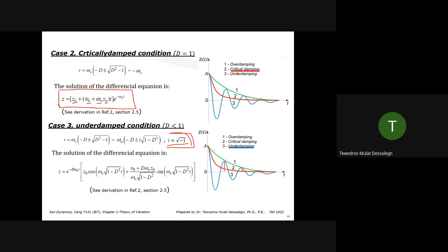The other two cases are something like a piston in hydraulic systems. A critically damped case has a high damping value. But in most natural cases, like soil, the damping ratio is about 15, depending on what type of soil you have, 10 to 20.